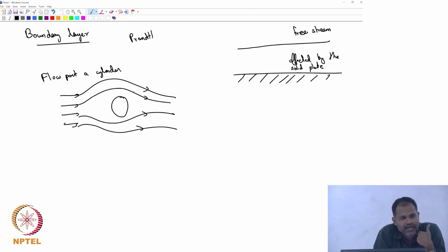Now we associate drag so much with viscous forces, but we also say that if you keep increasing your Reynolds number, viscous effects should become less and less important, and therefore we should be able to predict that drag force just from Bernoulli's equation. But when they did experiments, the experiments never matched the predictions from Bernoulli's equation. If you neglect viscous effects, the calculations were never correct.